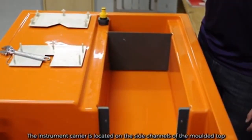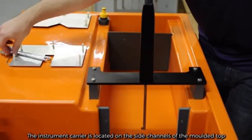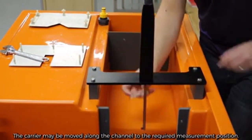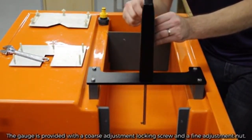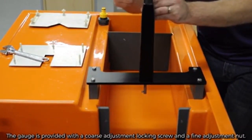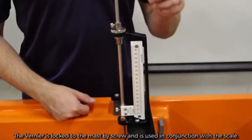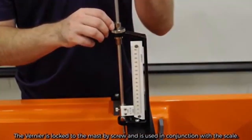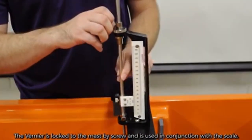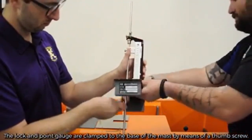The instrument carrier is located on the side channels of the molded top. The carrier may be moved along the channel to the required measurement position. The gauge is provided with a coarse adjustment locking screw and a fine adjustment nut. The vernier is located to the mast by the screw and is used in conjunction with the scale. The lock and point are clamped to the base of the mast by means of a thumb screw.